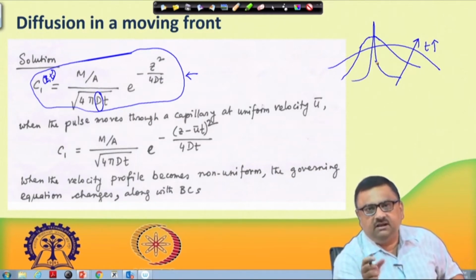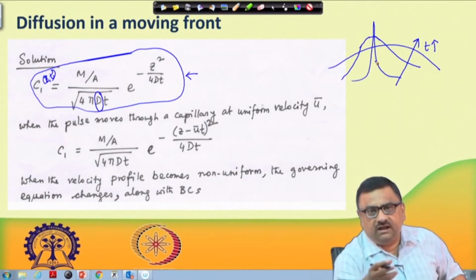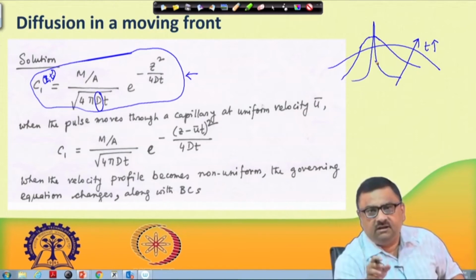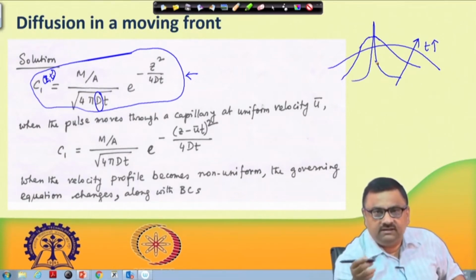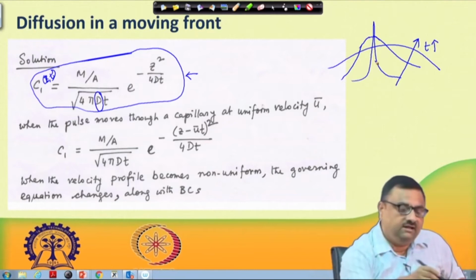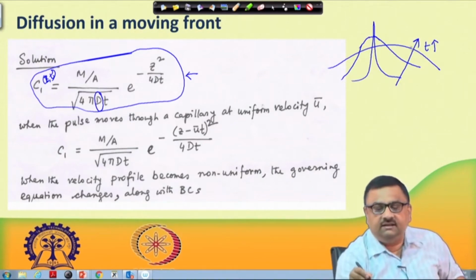Something with a very low diffusion coefficient, though supposed to be miscible, will mix if you leave it for a long time, but it will take a long time. The diffusion coefficient is the characteristic parameter which tells you how fast the molecules will diffuse. So naturally, if d is increased, I can see the impact here.